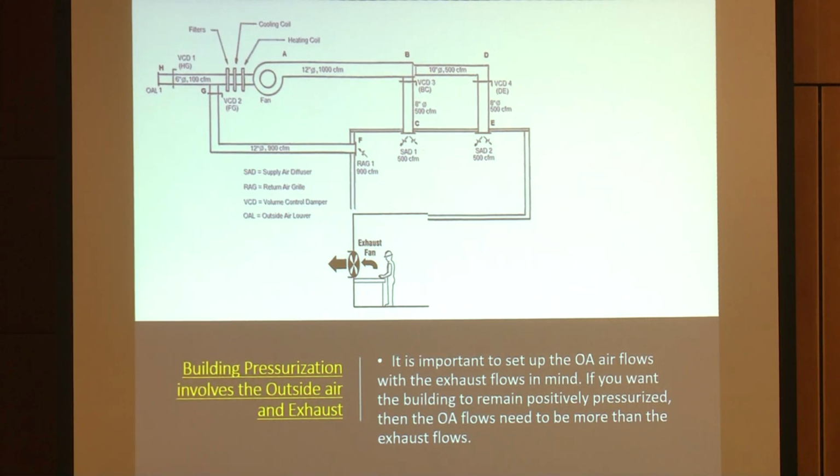You're going to look very simply at the air handling systems, which typically are supply going to a room. You've got outside air or ventilation coming in. You've got a return coming back around, and then you have some sort of an exhaust. Obviously, you need to check it, because if any one of those aren't working, you're wasting your time doing anything. You cannot test, adjust, and balance a system that any part is not working.